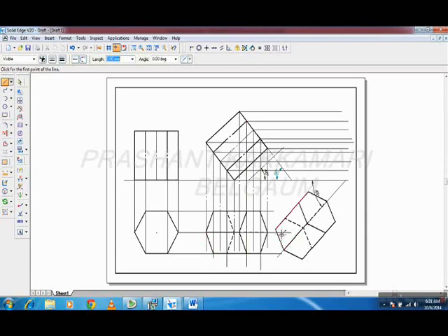So see here. Now here there are number of corners. There are 6 corners at the bottom, 6 corners at the top. So totally 12 projection lines should come from the bottom. So where they are cutting, observe. And properly click on the line when it is vertical, not at inclined.